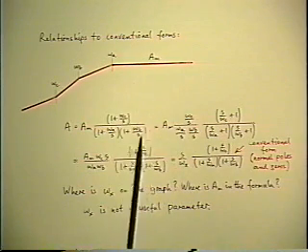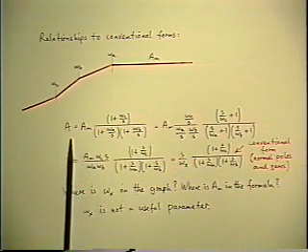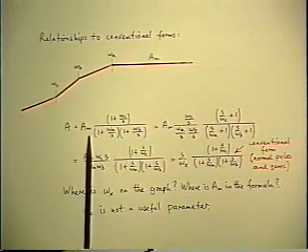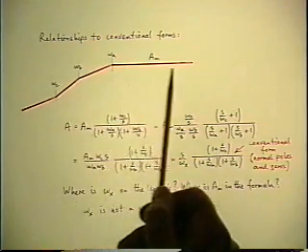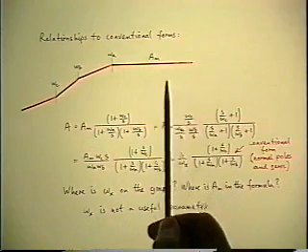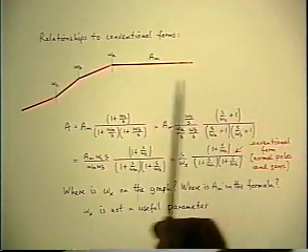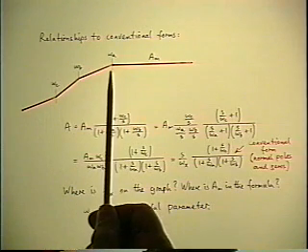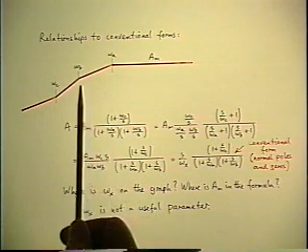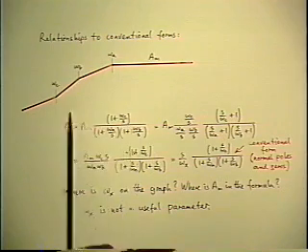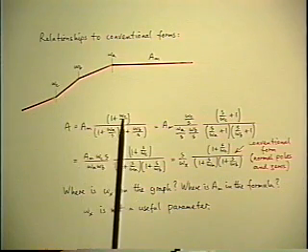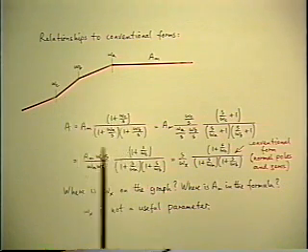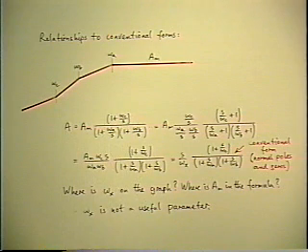So you start the expression by writing A equals A_M. That establishes this flat gain as a reference. You look up in frequency, nothing happens. You look down in frequency, and you encounter first the inverted pole at omega A, another one at omega B, and finally the inverted zero at omega C. So this is the format that I've recommended.